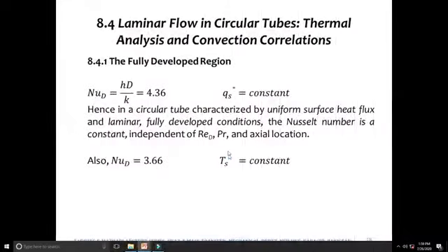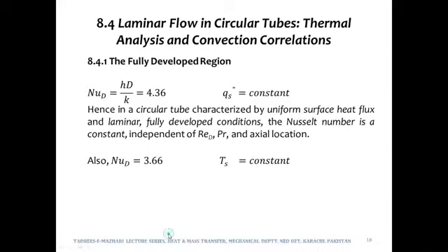That value is found to be, we are not going into the details and derivations, 4.36 for the constant surface heat flux condition, and 3.66 for the constant temperature condition.